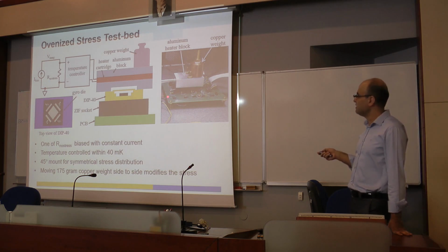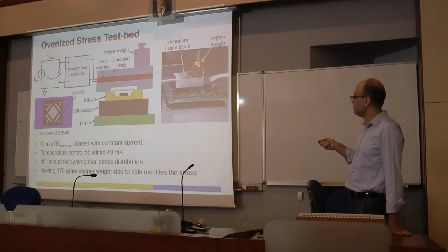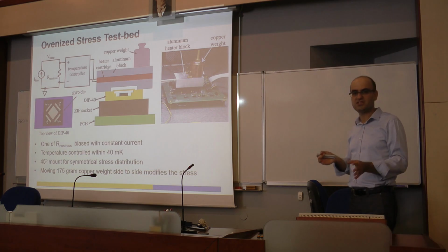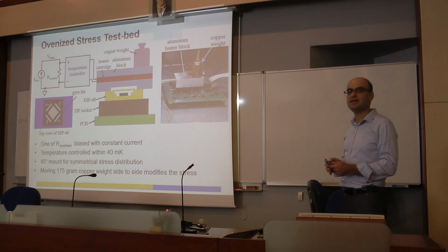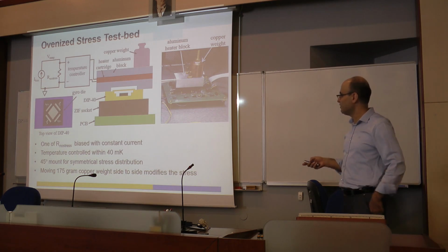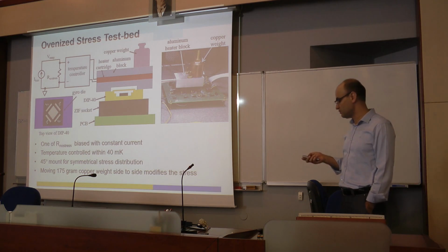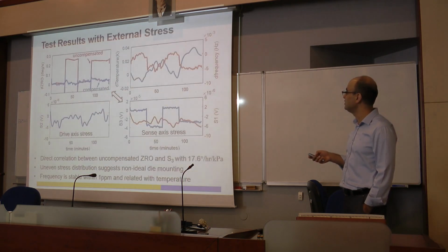And I fix the temperature here. And I also have a copper weight. What this weight does is I move it from left to right, right to left, and change stress while keeping the temperature constant. So we wanted to get temperature out of the picture so that we can see pure stress effects.